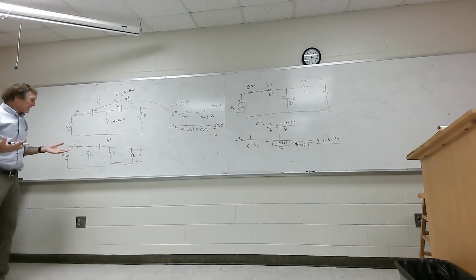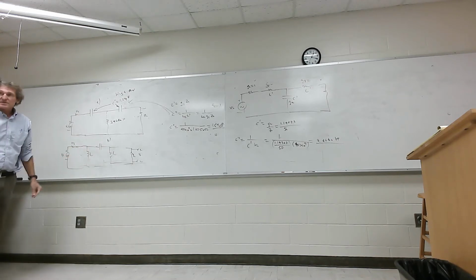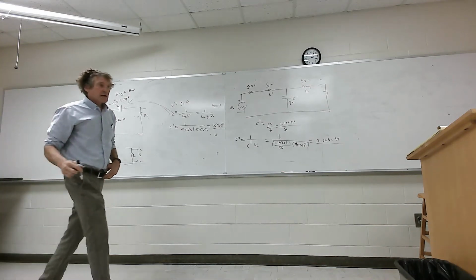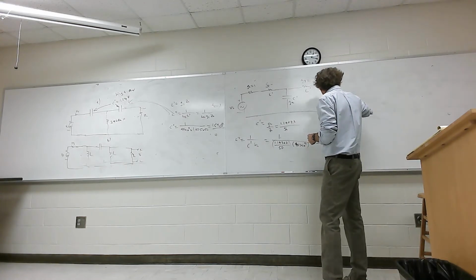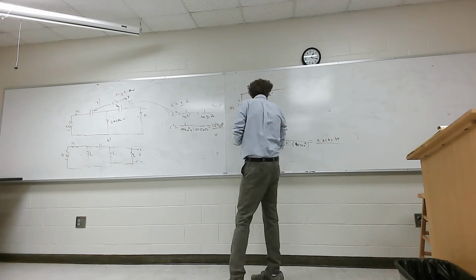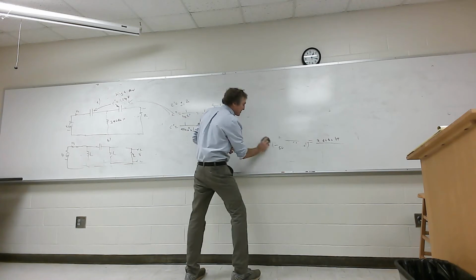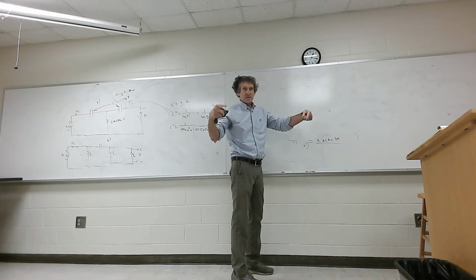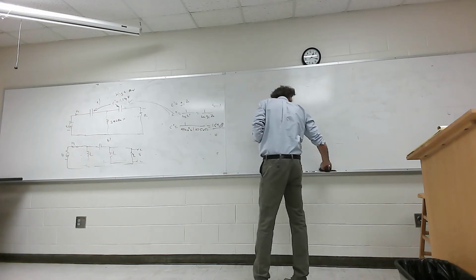Now, if you go over here and you want to get these values, we're going to do the low pass filter. Just listen to this though, don't mess this up. Now I have to put the pi low pass filter before I do the transformation. Y'all follow me in this? So I'm going to bring that one back up, and erase this. The biggest problem you're going to have with any of this stuff is just keeping track of how to get the right low pass filter first. Then after you get those elements, the transforms pretty much do themselves, even for the band stop, it's not hard at all.